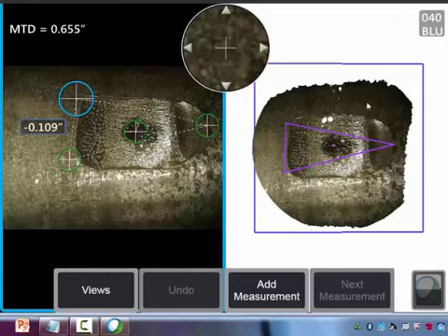So in the point cloud, we show this computed 3D surface data. And with that, we add spheres and lines that show you where your measurement cursors are placed on that 3D surface. And this blue outline is telling us where our depth measurement reference plane is located in 3D space.